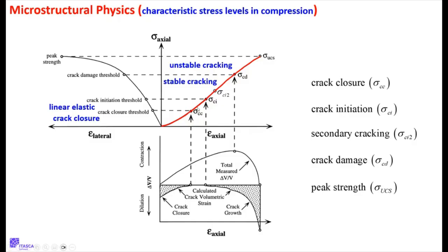Then you keep loading. And during this period also, you can do all kinds of cool things. You can put little acoustic sensors around the surface of the specimen, and every time a crack forms, you get an acoustic event, you get a little earthquake. And if you measure the arrival times at all those different places, you can back calculate the magnitude of the earthquake and where it happened. Those earthquakes are like little micro cracks, so you can record and locate those during tests. And I'm going to rely upon that information in the continuing interpretation as we move forward here.